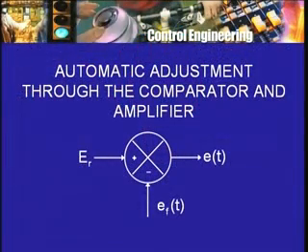Now, if we go back to our control system arrangement where we had the tachogenerator output, the reference input, the comparator device, and that signal amplified going into the motor which drives the load, with that kind of arrangement, can it handle this? So, no other changes to be made. Where is the automatic adjustment in that system? The automatic adjustment is through the mechanism of that comparator device.